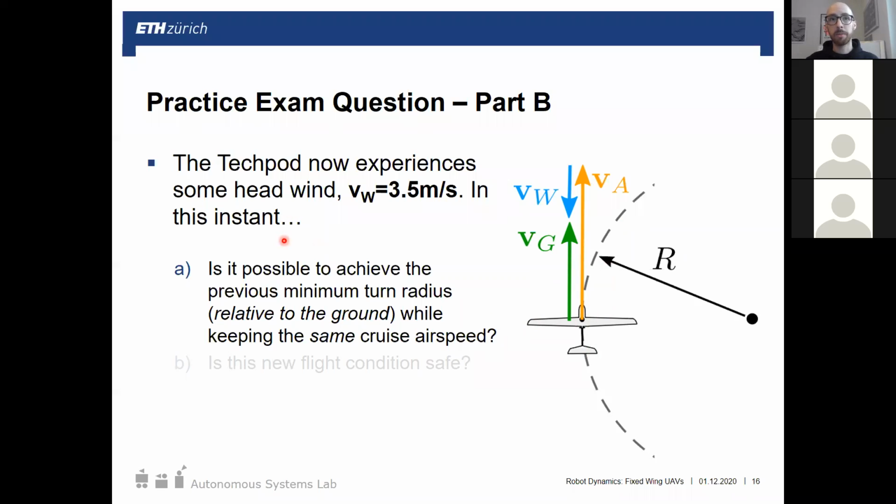This is actually important for guidance logic, for example. Like the L1 controller, you'll see in the exercise next week, it uses the ground speed as its feedback term. The reason it does this is exactly this point, that we're only considering, in this instant on this curve, what roll angle we need to achieve this curvature with the current ground speed. But Mike's totally right that as we continue on this curve, our ground speed's changing, and so we'll need different roll angles for every single point on that loiter radius.